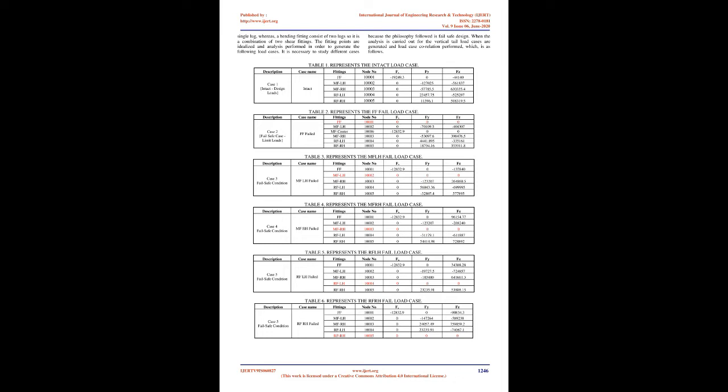Initially, the vertical tail is subjected to a limit load of 10,000 kilograms. The design load calculation is done in accordance with FAR 25.303, where the limit load is multiplied by a factor of 1.5. This yields a design load of 15,000 kilograms or 147105 N. This load is applied as a pressure load on the surface of the vertical tail in the preprocessor, which distributes the load based on the surface area and ordinates.